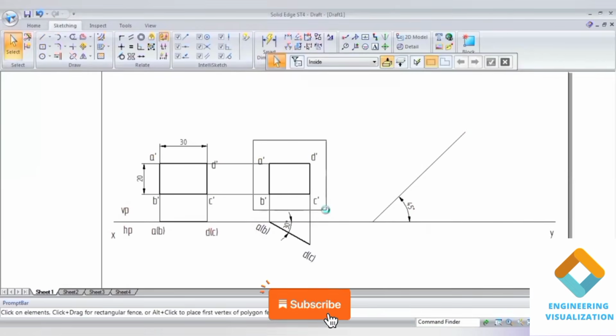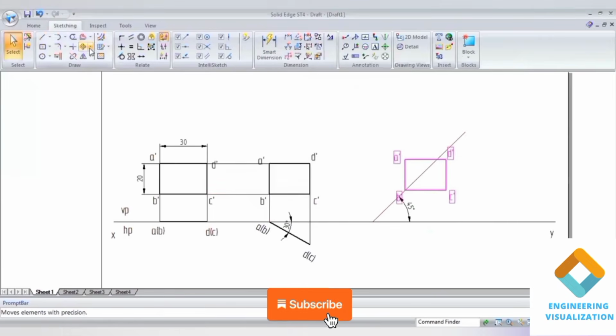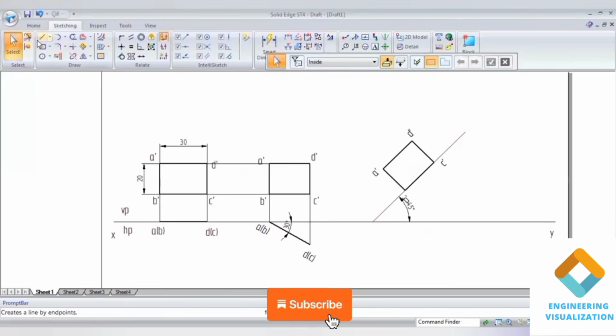I'll select this second position front view. Okay, create a copy of it and select the vertical edge here. I'll select this B dash. Go to rotate. Select this B dash to C dash and place it on the angle line. Then project downward to complete the final position.